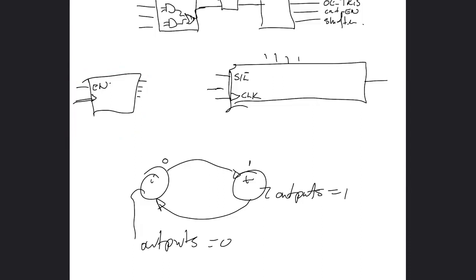So what I told the class yesterday is, over here, just put in a logic gate, like an AND gate, for example. Maybe you want to add inverters here if you want, but that's not necessary in this case. And this output here, I've called something like count max, or count reached, or transmit count max reached, whatever you want to call it. And the inputs into your state machine are really those. The current state, or present state, is the one input. The other input is, has it reached count max? And I'll show you why in a second.